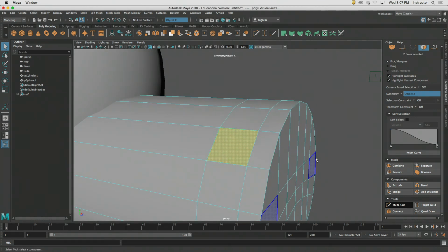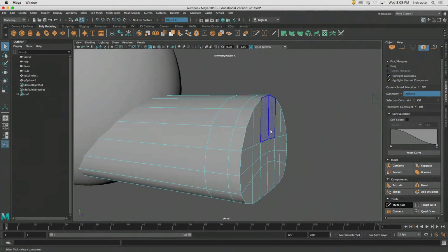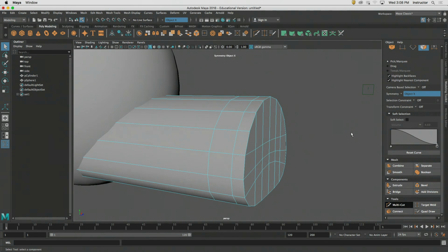So really what I would like to have is a shape that looks circular, okay, that I then can extrude out, okay? So I need to have some circles imposed upon my mesh, and it's really easy to do that. We're going to use a couple different tools here to get the end result, but the takeaway here is twofold. We're going to look at the details of the Insert Edge Loop tool, okay? In addition, we're also going to look at a tool called Circulize, which is really neat, okay? And I like Circulize very much.